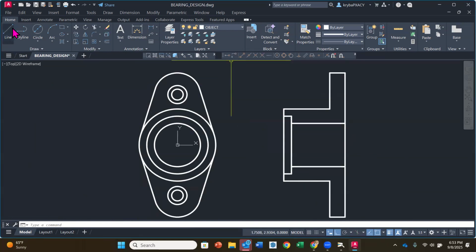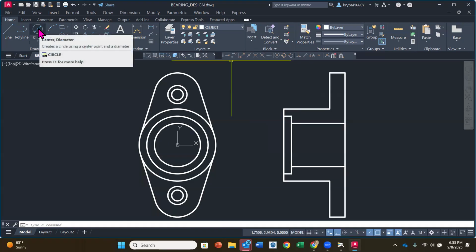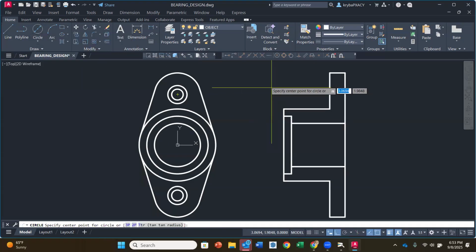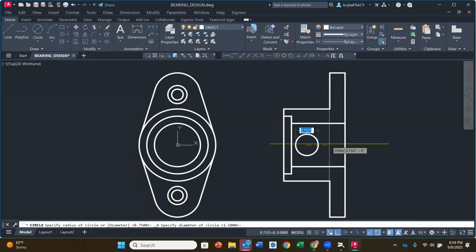So we're going to do a circle center diameter. So we have to start our command again. We're going to do a snap from midpoint, and we're going to activate that midpoint. Okay. And then now we're going to do the @ symbol, shift to -1.25, comma 0, enter. There, that looks better for center. And then our diameter is 0.375, enter. There we go. Okay. Not a bad idea to do a quick save.